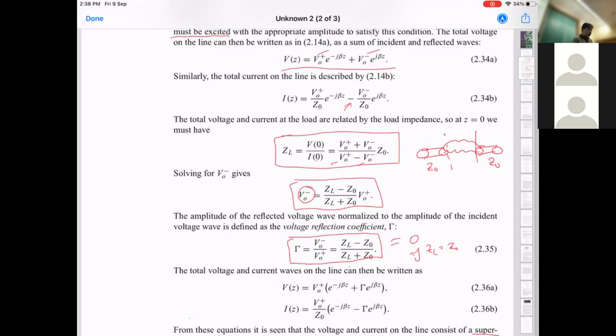Yeah, so you cannot do these kind of things, and usually there are special devices which enable you to connect one cable to the other, and they try to ensure that these waves don't experience any change in this impedance. So this is not very different in the context of light when you start thinking of light going through different mediums. So you want that refractive index to be exactly the same. Otherwise, you will get some reflection at that particular point.